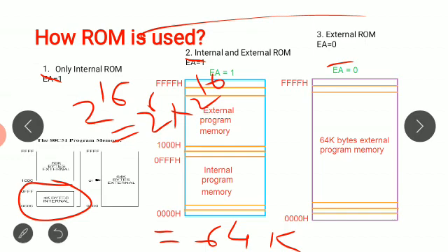In any of the general applications you see around you, traffic lighting or your washing machine or speed control of any motor and things like that, they don't require thousands of instructions for carrying out the application. Normally 300 400 instructions are sufficient. So that 4 KB is sufficient for doing a particular application.